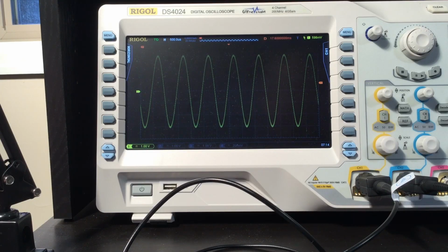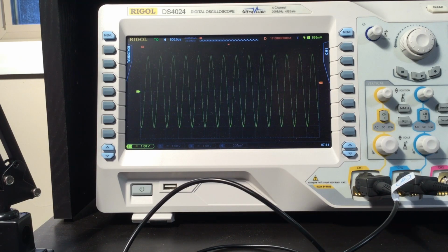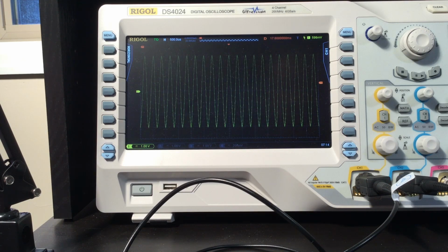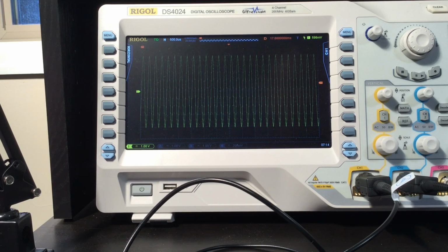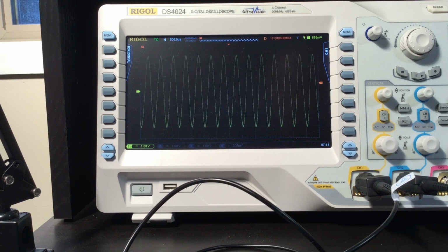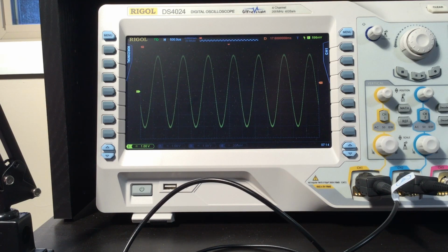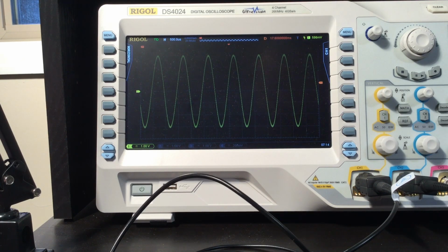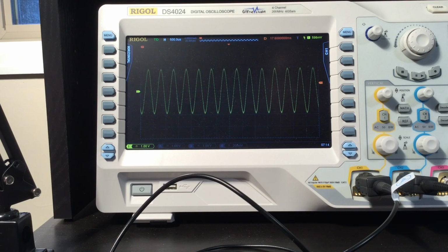Now let's go ahead and adjust the frequency, and I'm going to go from 1 kilohertz to 2 kilohertz to 3 kilohertz, and you notice it holds constant across the whole circuit. But let's look specifically now just across the capacitor and watch. You notice it's a little less than 6 volts, and as the frequency increases, remember the reactance of the capacitor is changing.